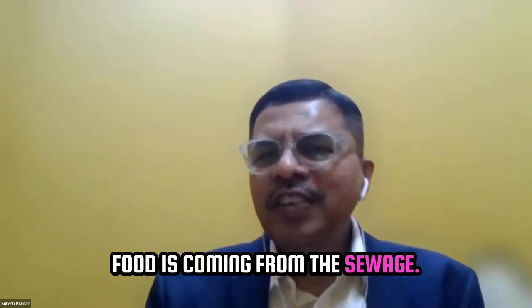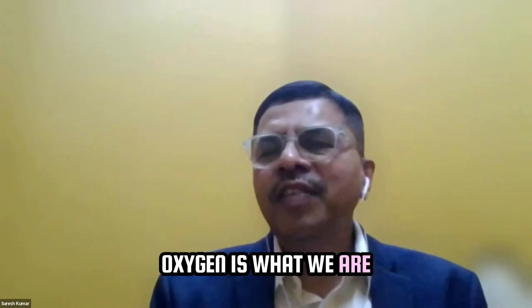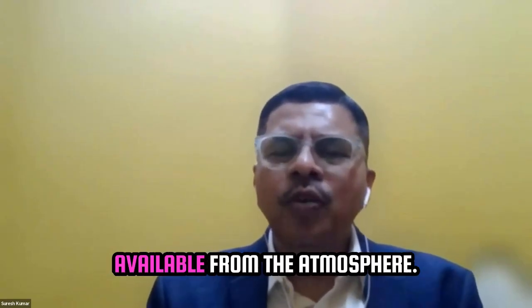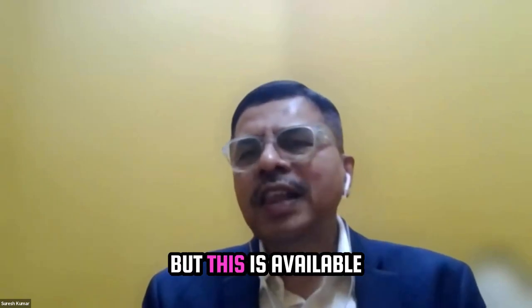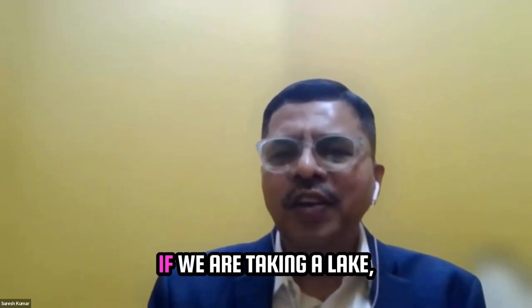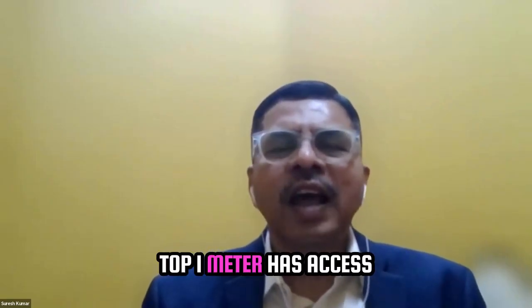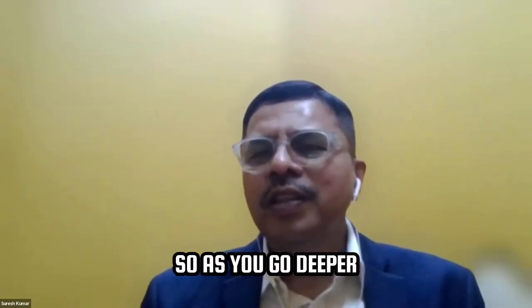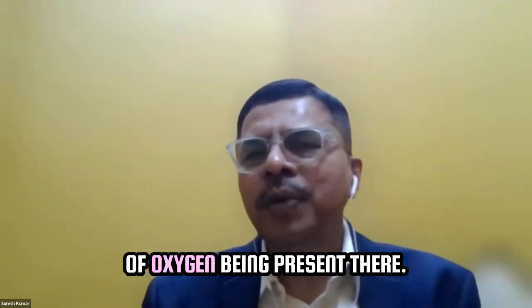Food is coming from the sewage. Oxygen is what we are giving externally. A small quantity of oxygen is available from the atmosphere, but this is available only to the top layers of water, maybe up to 1 meter depth. If we are taking a lake, the top 1 meter has access to atmospheric oxygen. So as you go deeper, there is no possibility of oxygen being present there.